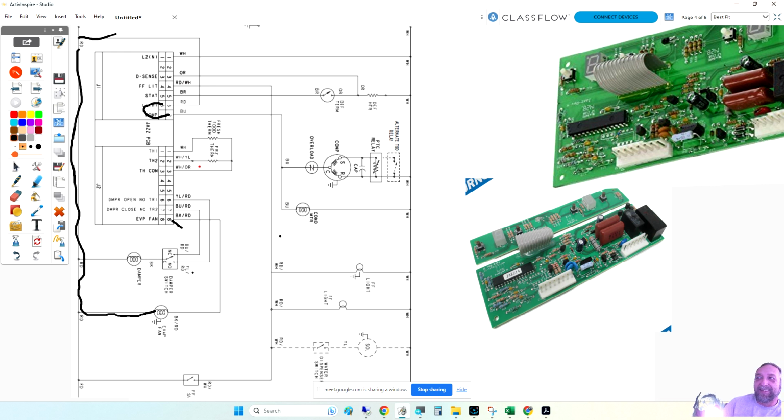You need neutral. I need a neutral, so I have to go over here to what? Pin 1, over here with a wire. That fan will not work if I go red to red, because I'm putting 2 line 1s to it. You see that? Yeah, that's what I originally thought.